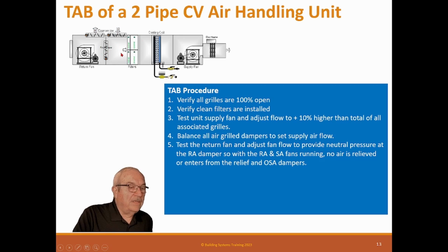If you have this fan pushing too much air, this is going to be positive pressure, and this becomes positive pressure, then this is not going to be outside air. This is going to be a relief damper. So if this is positive pressure, it's going to be relieving air. It needs to be negative pressure, so this sucks in air. If this is a negative pressure, so if this has way too little air and this fan is overpowering, this fan is sucking air out of here, this is now an outside air damper. So if you don't have this set up correctly for these pressures, these two are either relief dampers or they're outside air dampers. And that's a problem.